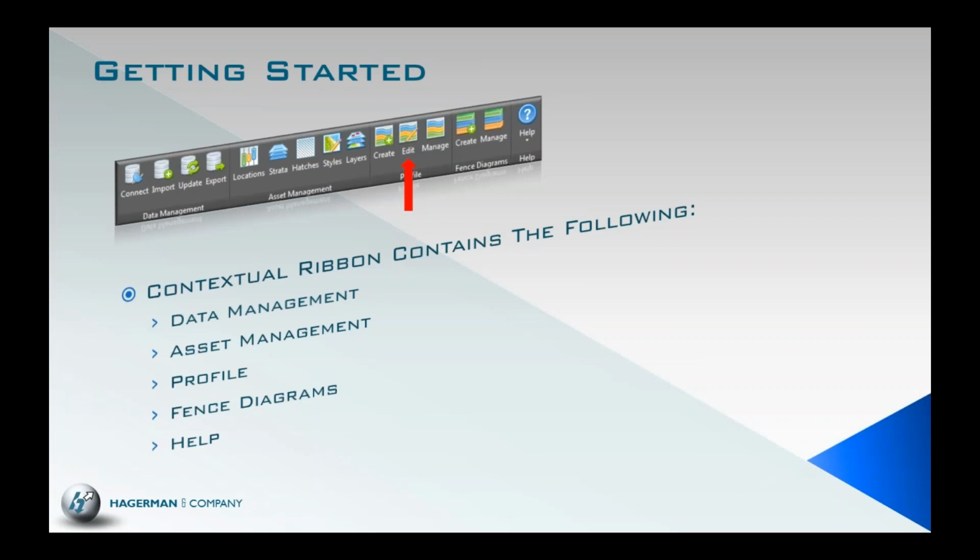Okay, we can edit. So we're going to be able to edit our Civil 3D profile view. Again, pretty straightforward, right? We've all done that before. So once a view's been created, the editor tool allows us to change what is actually displayed on that profile. So we can turn it on and off, much like we can with our pipe networks. If you're familiar with that, this is going to make a lot of sense to you.